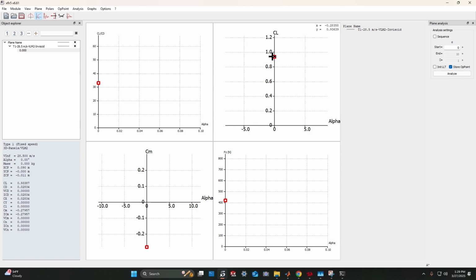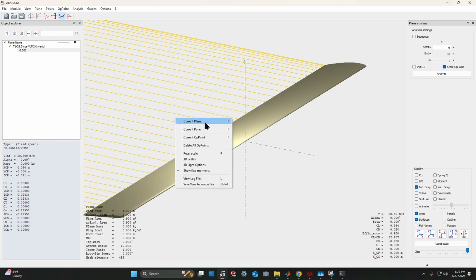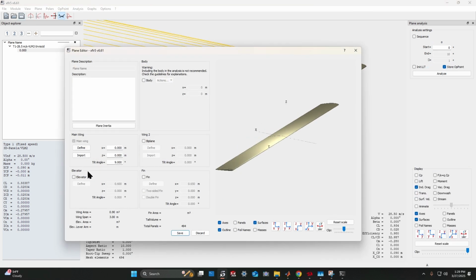Yes, and that's about 0.1, so I might want to set the tilt angle of my wings to 9 degrees. I would probably not go much higher than this for a tilt angle. Another option could be that you have a tilt angle of, say, 5 degrees and fly it, and the angle of attack you're going to fly at will be 4 degrees, approximately.